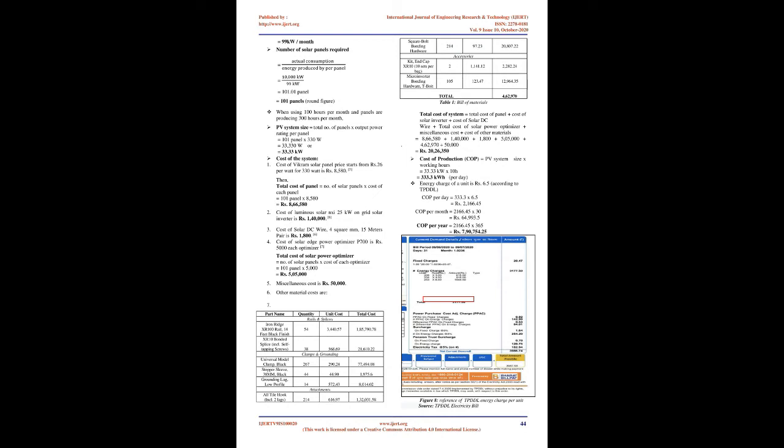The right position or direction of the solar panel decides the efficiency of the solar panel. South is the perfect direction for facing solar panels to absorb huge solar radiation. East and west are good directions. The panel should not be placed in the north direction because India is situated in the northern hemisphere, so south is the perfect direction for placing solar panels instead of north.